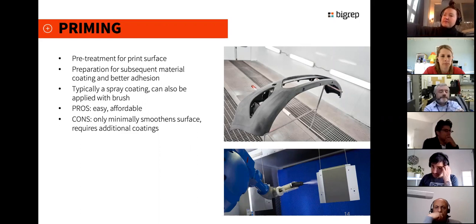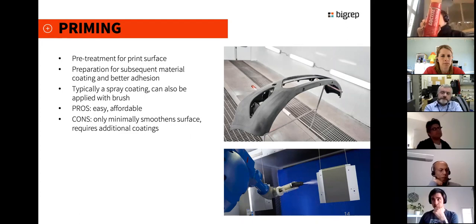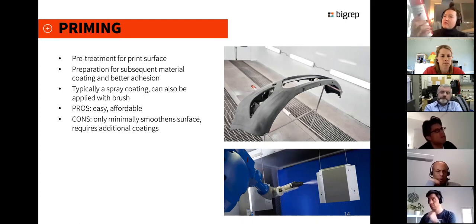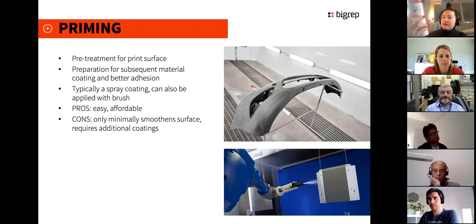I have one here I've used before. This is by Loctite. I have a few samples of materials here from them. This is actually by Henkel, but Loctite is the brand. They make a number of 3D printing specific materials, and these are pretty cool. They call this a smoothing beige primer. So in 30 minutes, you can already sand it if you like.